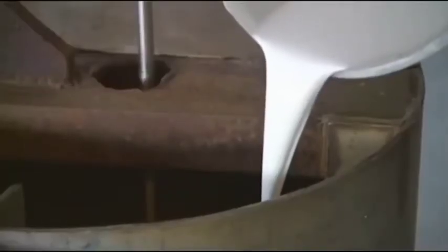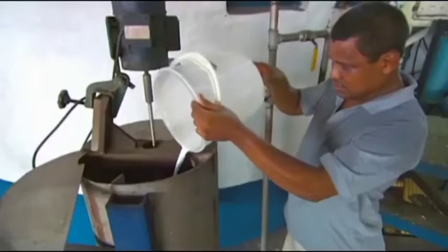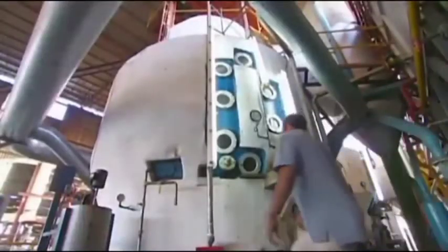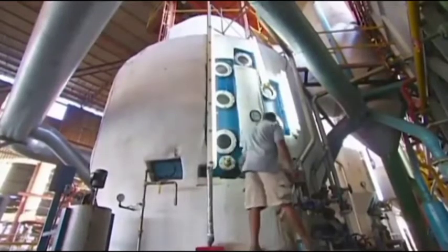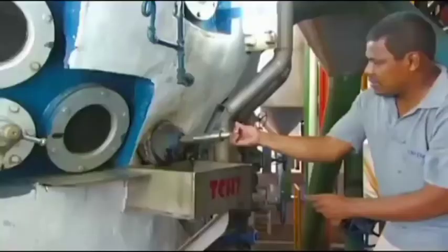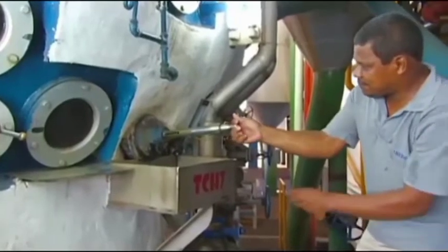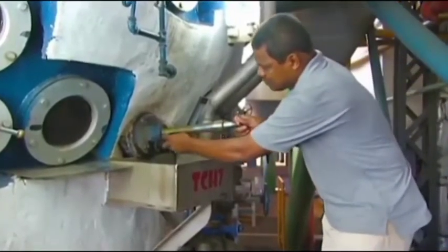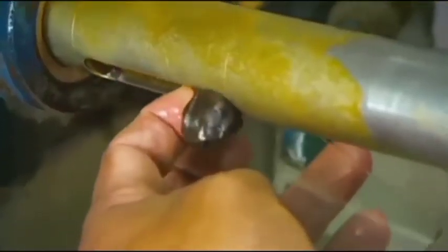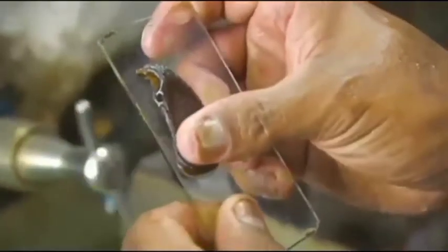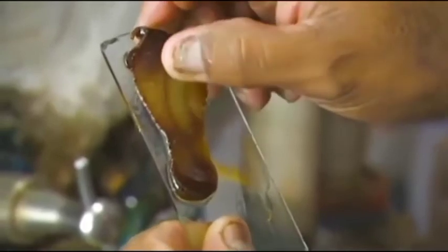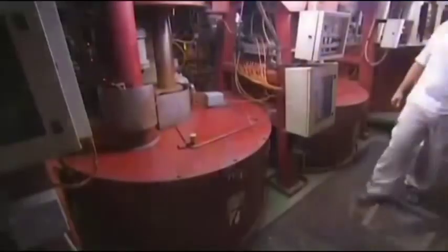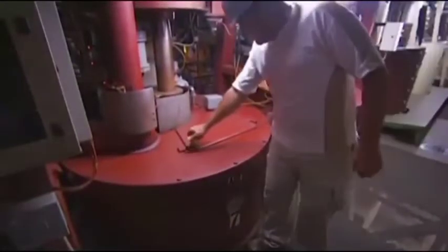Groove. The mill roller has a fairly deep groove between 40 and 60 mm with a groove angle between 35 degrees until 60 degrees. Additional grooves are made between these grooves, which are deeper by 20 to 25 mm, called Messchaert grooves, with the aim of accelerating the flow of juice out of the rollers.